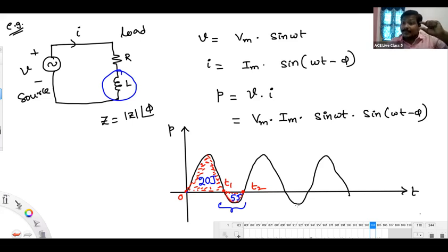In place of inductor, if we keep a capacitor, it stores the energy in one half cycle and delivers the energy back in the other half cycle. So what is that capacitor doing now? Is it absorbing reactive power or delivering reactive power? Both. It stores, charges, discharges, continuously.